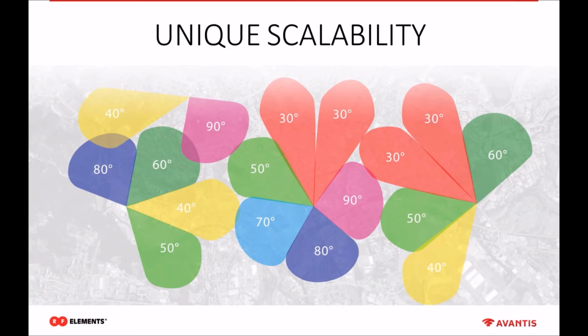So, for example, if you have a 120-degree sector and you have a lot of customers there, you will probably face really bad throughput and performance of the sector. By using a symmetrical sector antenna, you can split this 120-degree sector into four 30-degree sectors, which means the same amount of customers will be served by 4 APs, so your performance will go up as well as throughput.